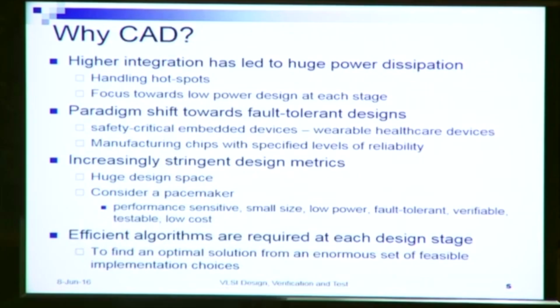Also, higher integration, as we said, many transistors within a chip, higher integration will lead to huge power dissipation, because all these transistors within the chip, each of them will leak power, and hence there will be huge leakage power, and correspondingly we will have hot spots generated within the chip.